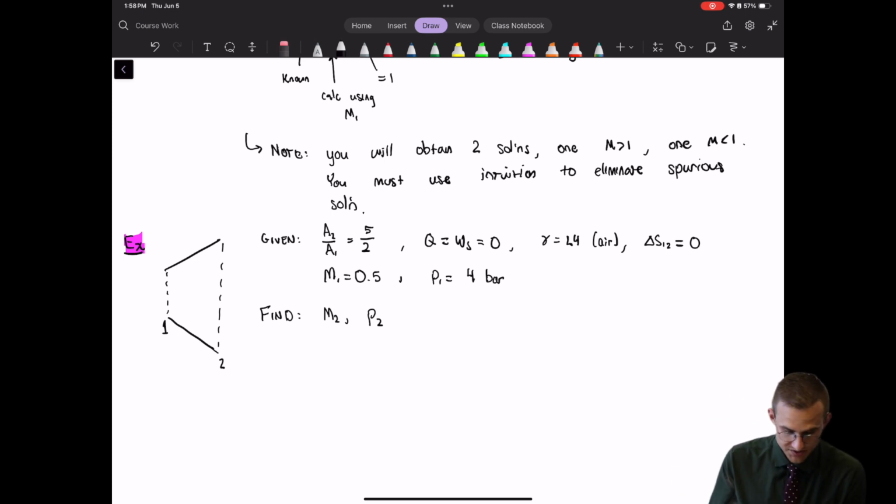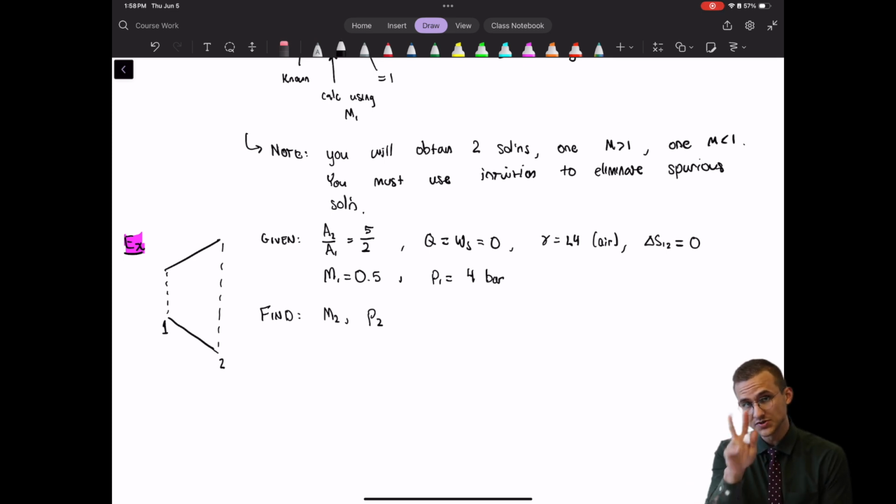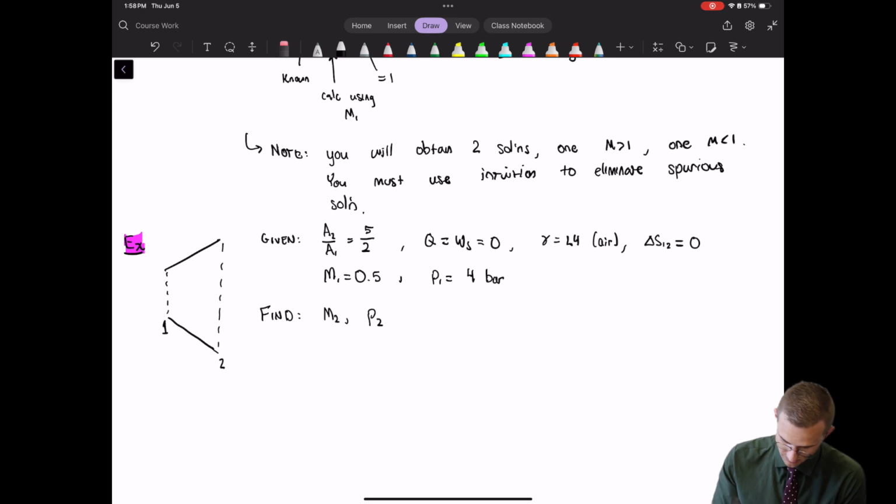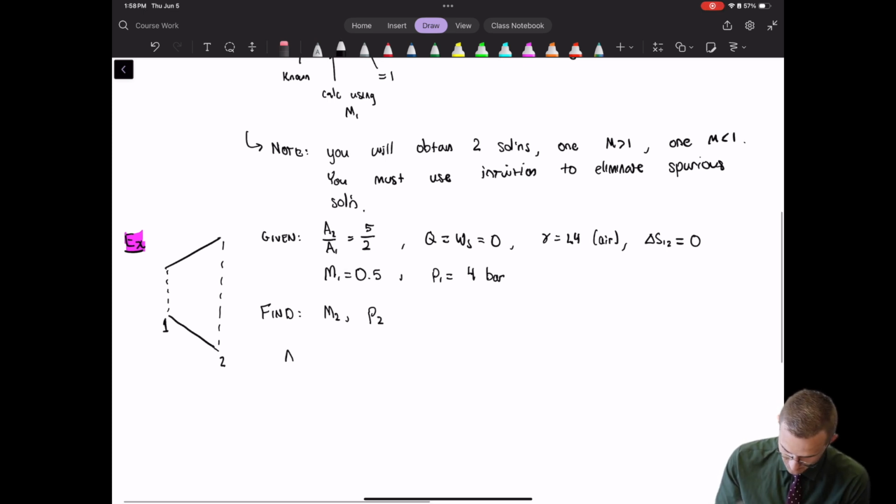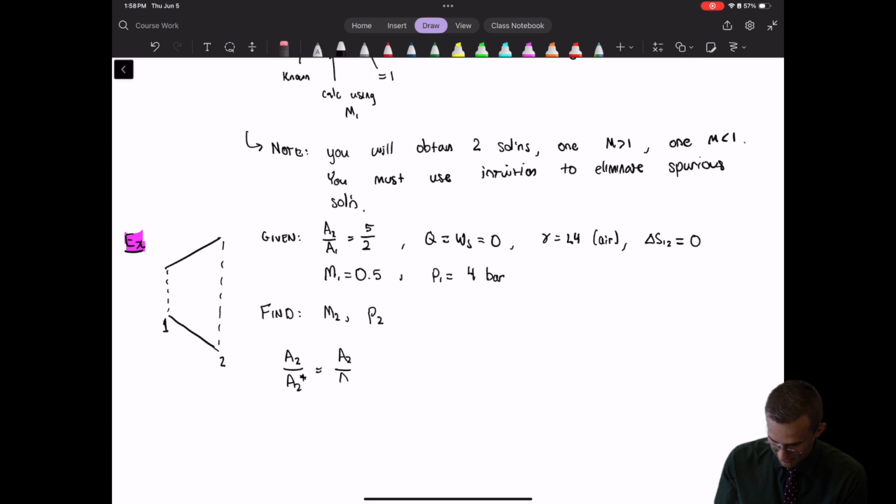Because we have the Mach number M1 and we have the area ratio, we should be able to find M2 with those two pieces of information alone. Like we did above, we expand out and do this canceling fraction deal, where we pull out information that we know. We know what A2 over A1 is; that value is given. We multiply that by A1 over A1 star, which can be calculated from M1.